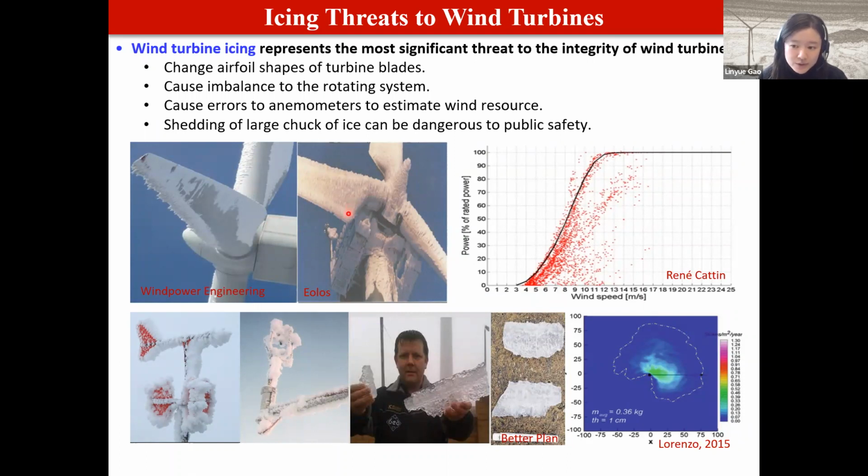The downtime due to icing may last for days or even weeks, which can lead to significant economic losses for wind farm operators. In addition to the power output penalties, the uneven ice accretion along the wind turbine span can also cause edgewise vibrations or even imbalance, which may significantly shorten the lifespan of wind turbines. In addition to those direct effects, icing may also cause secondary effects, such as safety issues due to falling or projected ice chunks.